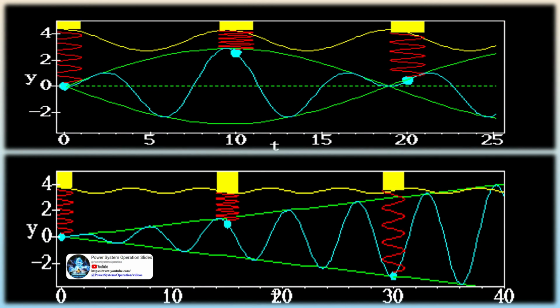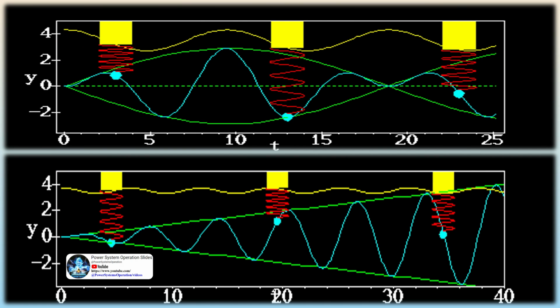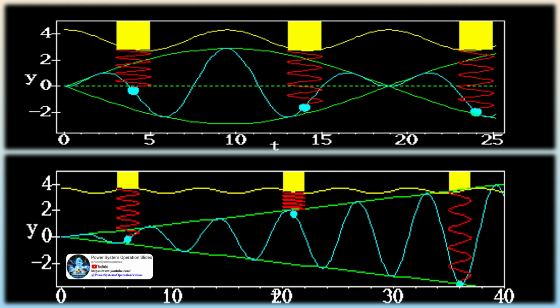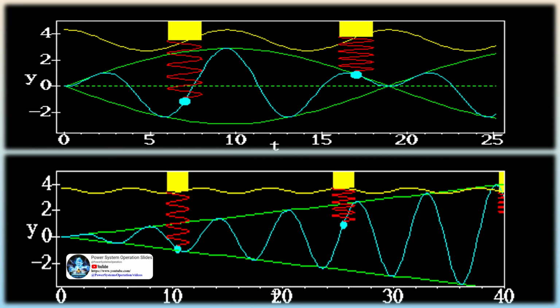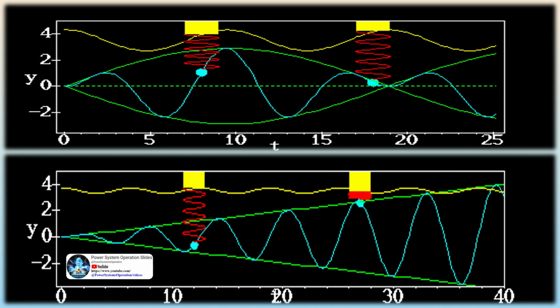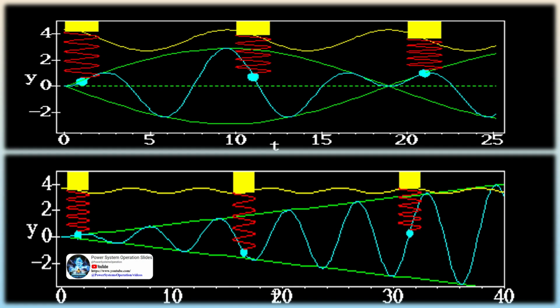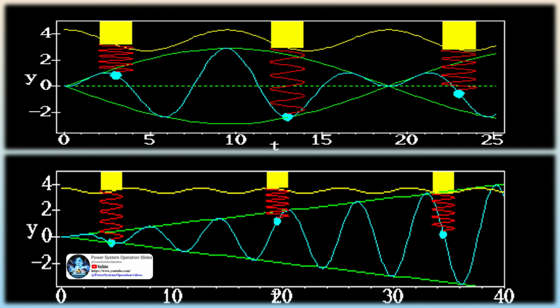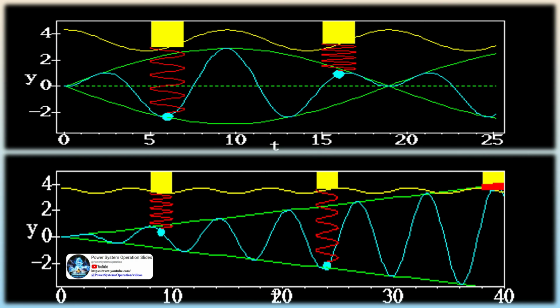A 1000 megawatt generator with a properly tuned PSS may only contribute 1 to 2 MW of damping. This small amount of damping from an individual unit is not enough damping to make much of a difference. PSS are typically installed in the majority of larger units in the problem area. The combined effect of many PSS has a significant impact in damping oscillations.